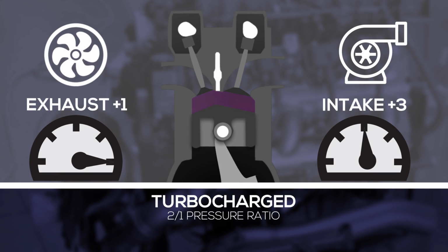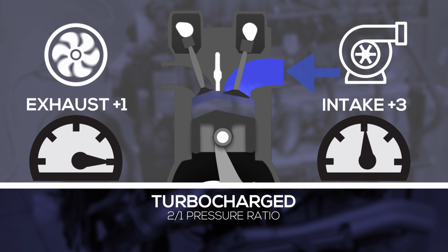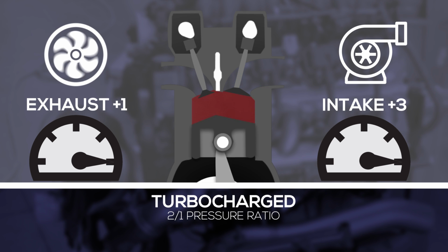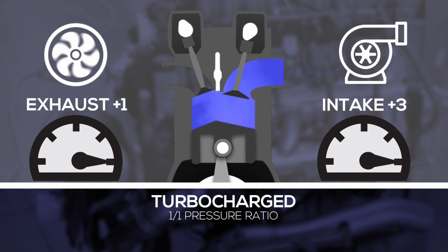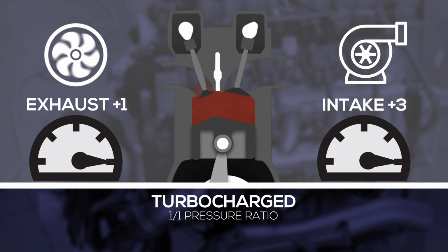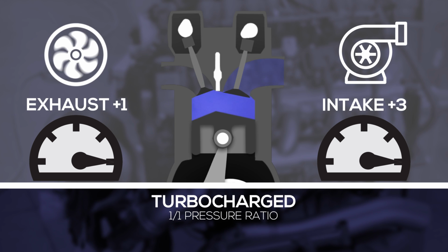Modern, efficient turbocharger designs are far less restrictive on the exhaust side and have a pressure ratio closer to a naturally aspirated engine's 1:1. But pressure isn't the whole story. Now, instead of dealing with high pressure, low pressure, we're dealing with elevated pressure on both sides, high density on both sides, and we're back into more of a system that's working like normally aspirated, using the piston motion, using some wave tuning to create the mass flow through the system, but at lower velocity and less valve timing.